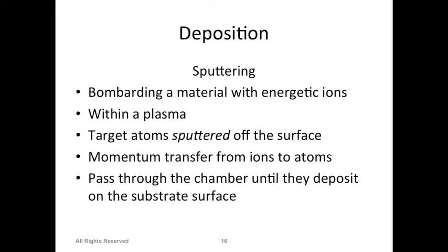We don't want to provide them high acceleration or energy, so there is a possibility that they might get implanted inside your target. But we want to give them enough energy so that they can go and hit your target, deposit some energy as heat and some energy as mechanical energy to dislodge some molecules or some small chunks or atoms from the surface of a sputter target, and those now removed chunks will come and fall down on your wafer, which in this case will be sitting at the bottom.